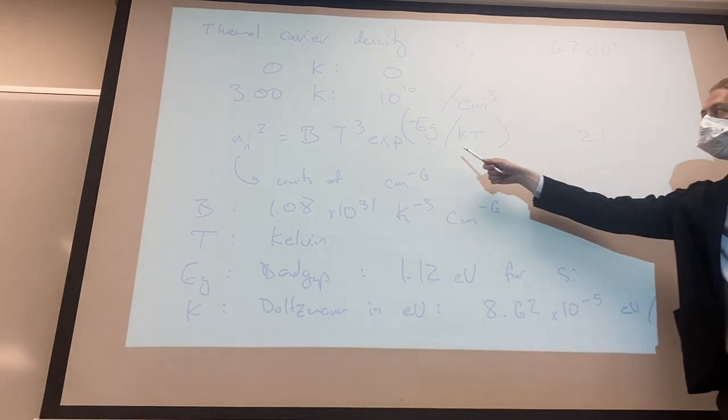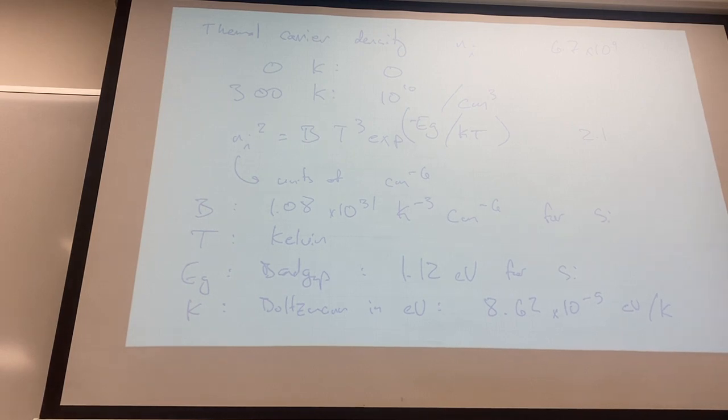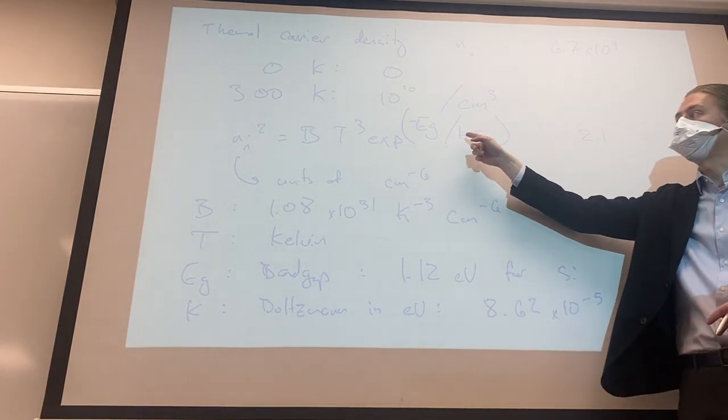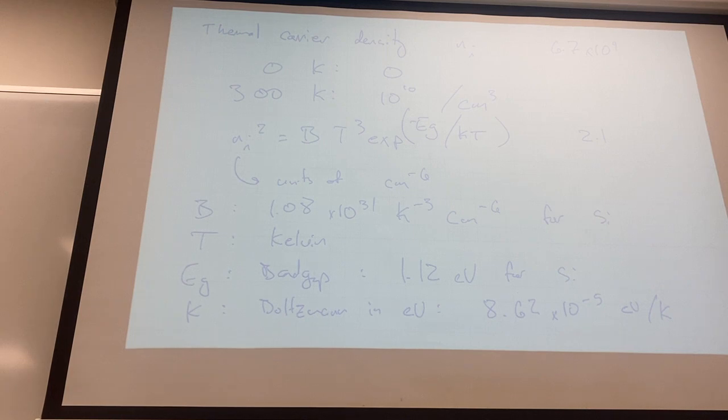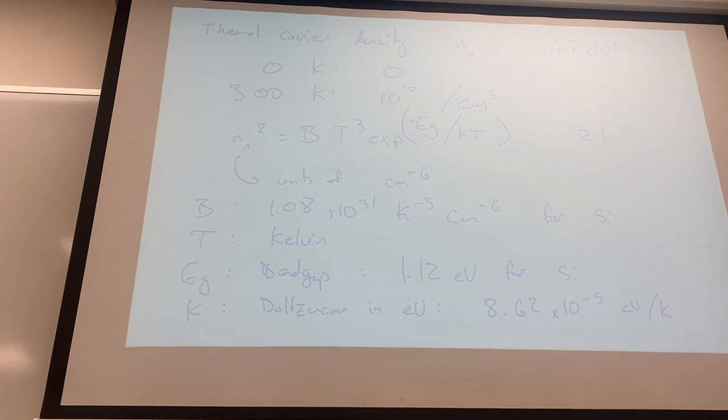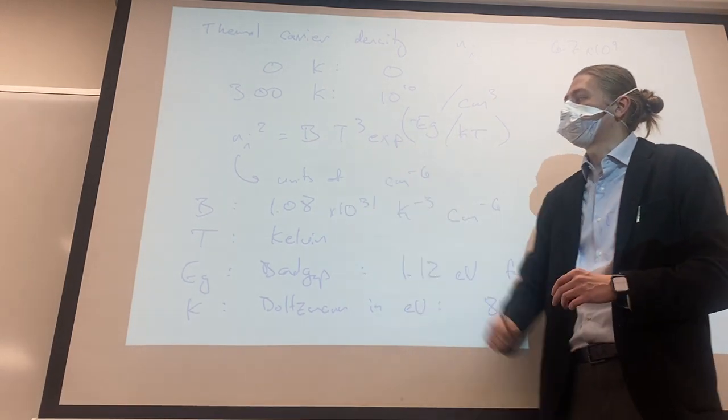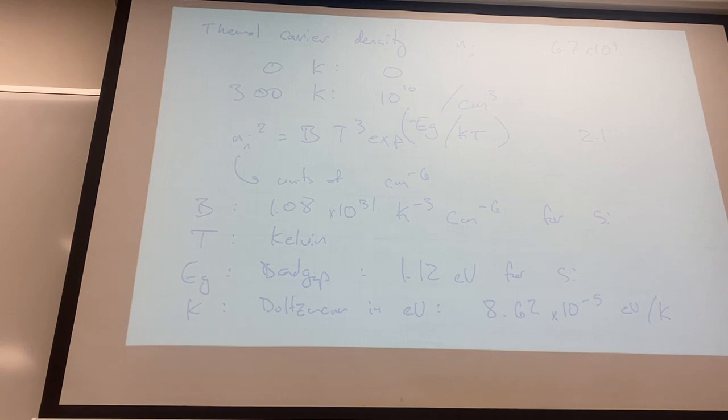Something with a wider band gap has a much higher temperature ceiling. And that's problem 1B in the homework: just turn the crank again with a different band gap value and see how much hotter you can crank it up. Silicon carbide, which is the material of interest in the homework, is what you put in turbine engines. You put that inside of nuclear power plants. It can get so fantastically hot and still operate just fine because the number of intrinsic carriers is still so low at really, really high temperatures. Now, the answer you get in problem 1 is probably going to be way higher than it should be because I've given you a new band gap and not a new material parameter here. But it should give you a sense of the trends anyway.